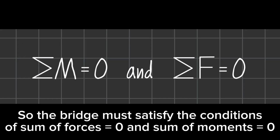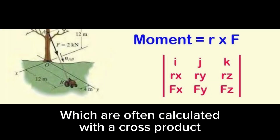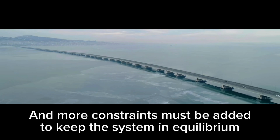the bridge must satisfy the conditions of sum of forces is equal to 0 and sum of moments is equal to 0, or more precisely, sum of forces in the x is equal to 0, sum of forces in the y is equal to 0, sum of forces in the z is equal to 0, and sum of moments in the x is equal to 0, sum of moments in the y is equal to 0, and sum of moments in the z is equal to 0, which are often calculated by cross products. If not, then that means the system is unstable and more constraints must be added to keep the system in equilibrium.